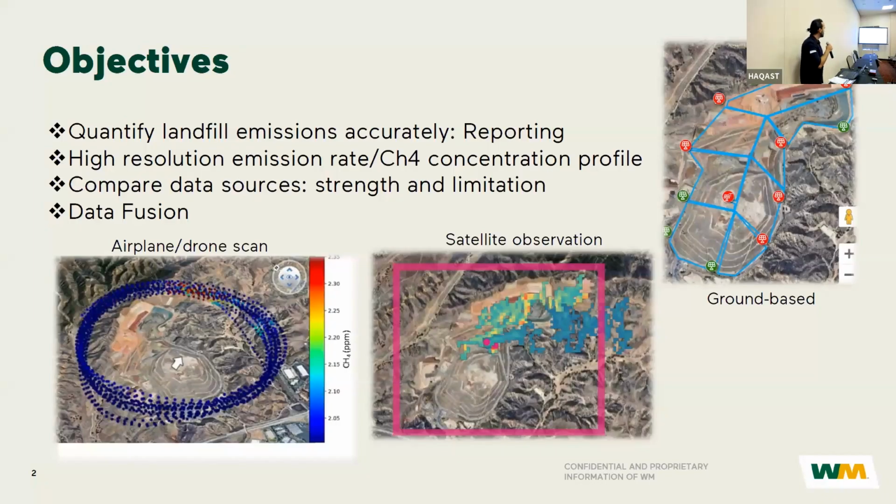So the objective of this project is to quantify the landfill emissions accurately. And by accurately, we mean with the lowest uncertainty possible. Right now, the methodology to quantify methane emissions in terms of emission rate is related to oil and gas refinery projects. There are point sources, there is a flare, and it's much less complicated to correspond a ground-based concentration to a flare emission rate, or vice versa, through different models such as Gaussian models and so forth.